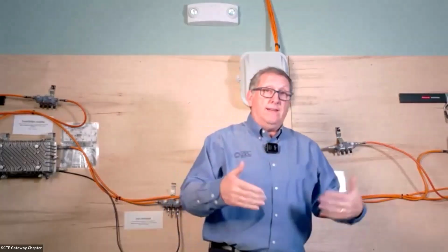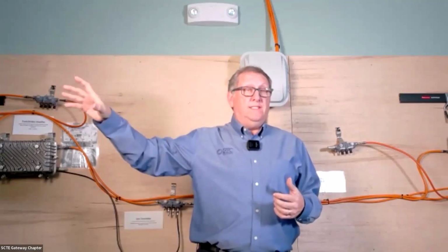Right. And so with the world of SFPs, it used to be that the transmitter in the node in the HFC world was a lower powered transmitter than the one coming back to the head end. Because the head end receivers were more expensive gear, they could receive a lower light level and still work. Whereas the field receivers were looking for a 0 to +1, a higher input, to have better noise performance. And it was in an environment that they had to maintain.